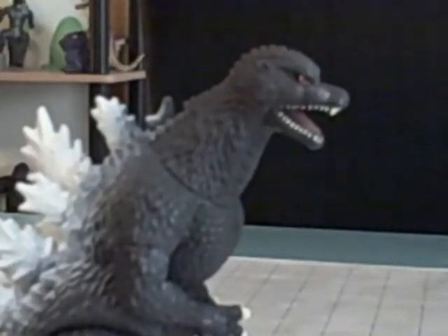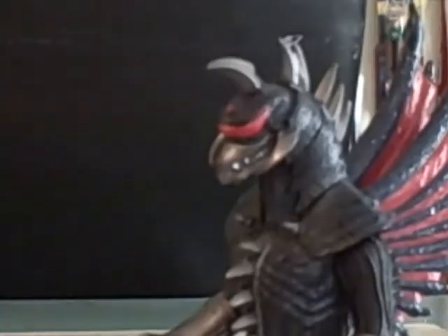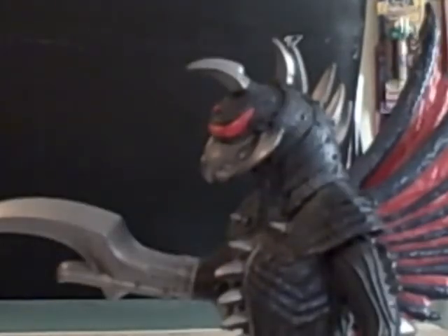I know what a dead load is. It's the weight of the structure, like floors and roofs. They're always there. And a live load is something like people, furniture, or equipment. They're loads that can move around or change weight, maybe even mass. You also have to remember dynamic loads. They're moving loads, like, say, traffic over a bridge.